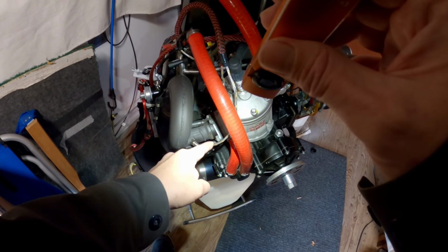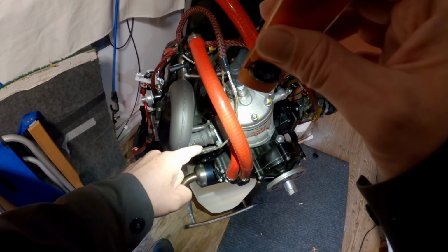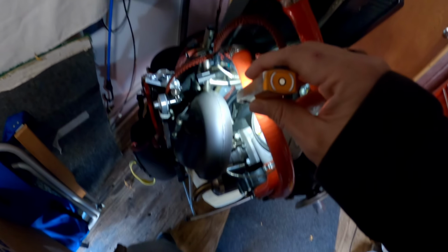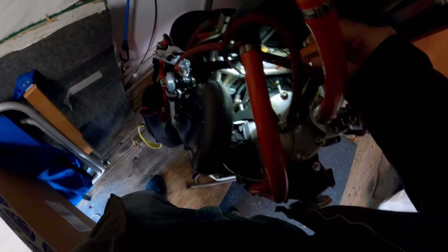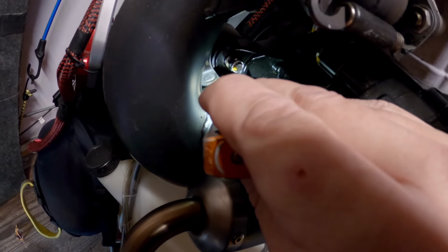So in order for me to know for sure in my mind and not go off hearsay, not go off the manufacturer, I installed the wideband oxygen sensor. You can see it's in the fat part of the pipe, down in here. I welded on a bung, and there's my oxygen sensor in that location.